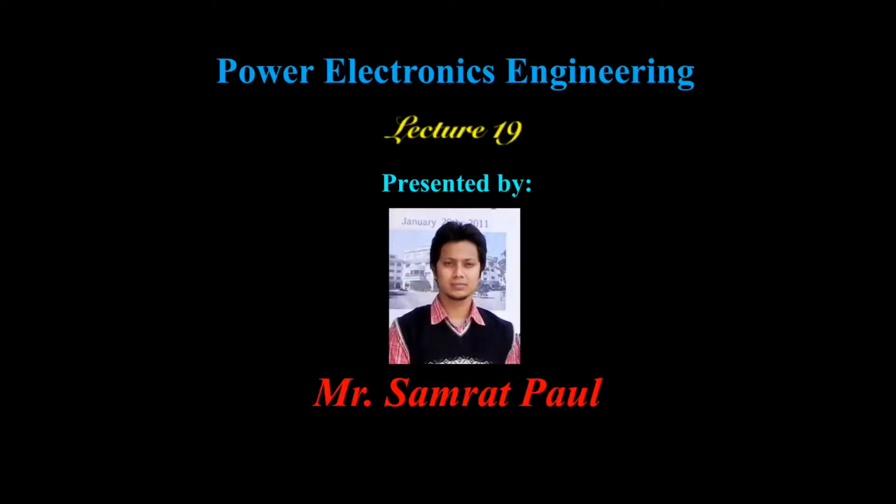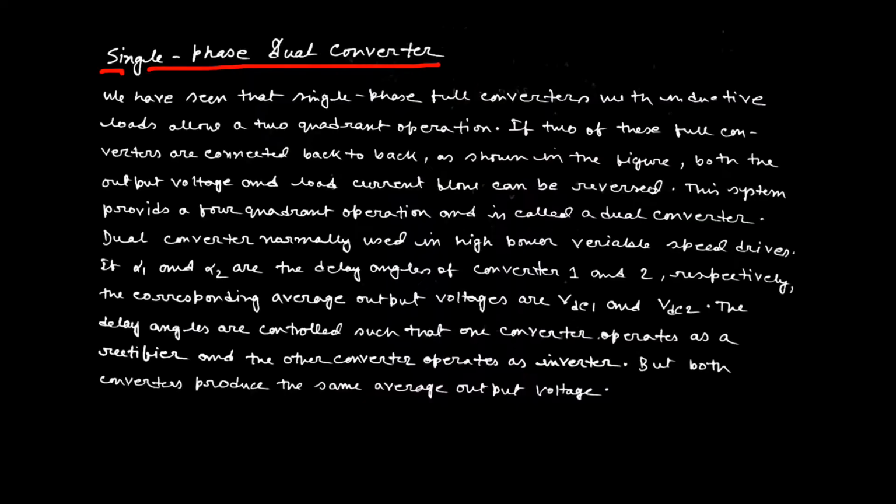In this lecture session, I am going to present the topic on single-phase dual converter. In my previous lecture session, we found that single-phase full converter with inductive load allows a two-quadrant operation, that means quadrant 1 and quadrant 4. When the inductor starts storing energy inside it, it can provide the first quadrant operation in which the voltage and current both are in positive direction.